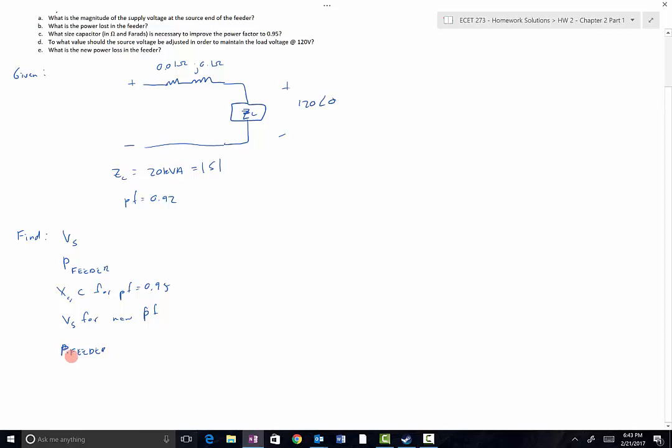If you're curious about this, what happens is that we set the voltage of, say this is a transformer or something, in a power system. We'll set that voltage, and then there'll be a voltage drop across the line due to the current draw by the load. So you have to increase the voltage at the input end to get the appropriate load voltage here.